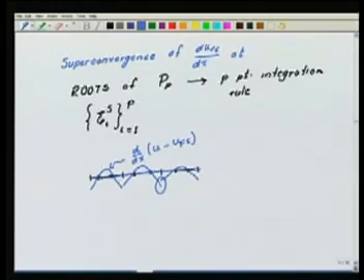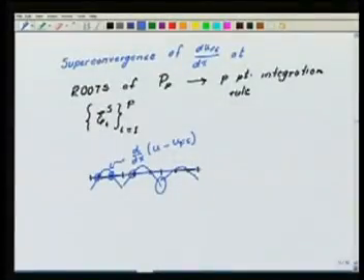Further, at the interfaces, I get a jump in the derivative of the finite element solution, which I do not want physically, because it leads to a jump in the axial force that we obtain. So, how best can we now use this information about these points to create a better derivative information? The simplest possible way is the following.